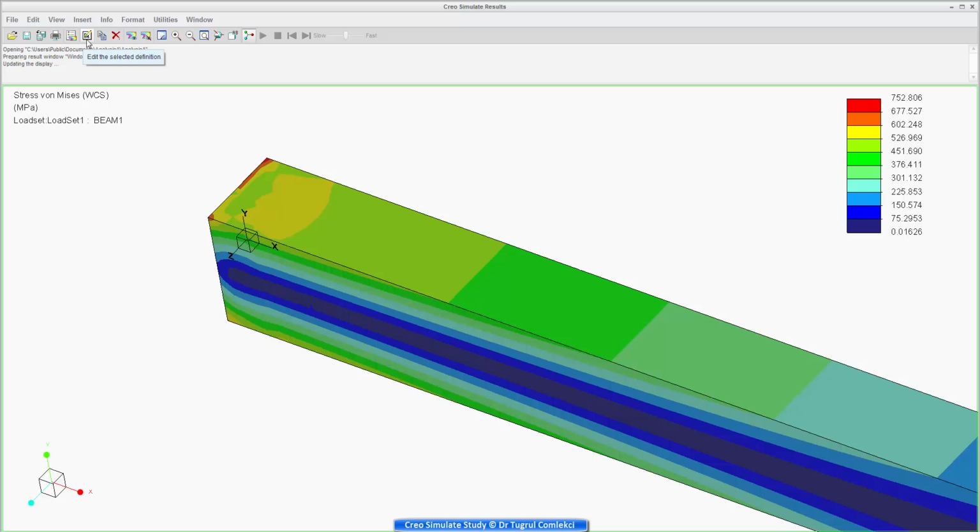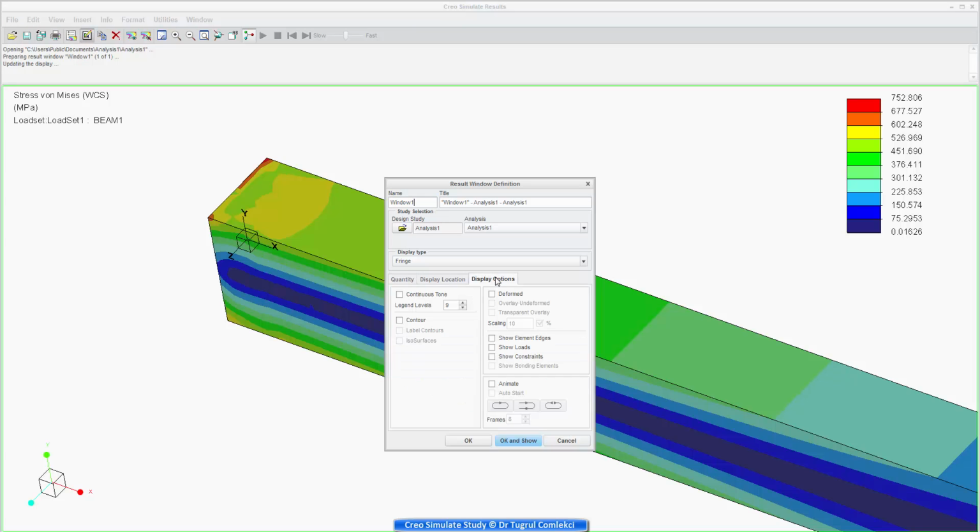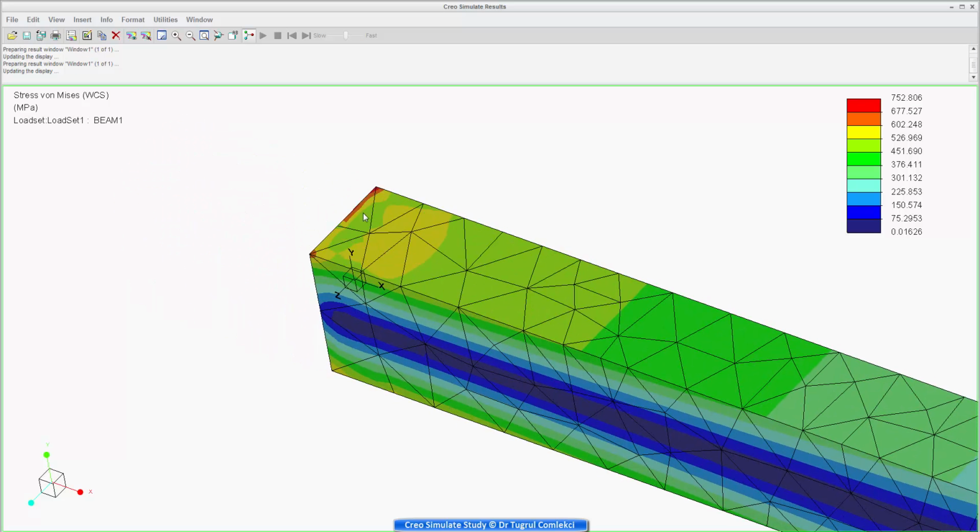We can look at the element shapes, show element edges. You can see that there are a few P high order elements there. It can be further refined there, and as more elements are put in or more higher order elements are created there, you'll have higher stress concentrations. So we can do dynamic query, and we can see that the stresses are ranging from say 520, 540, and then the boundary condition here is affecting the stress in this area.